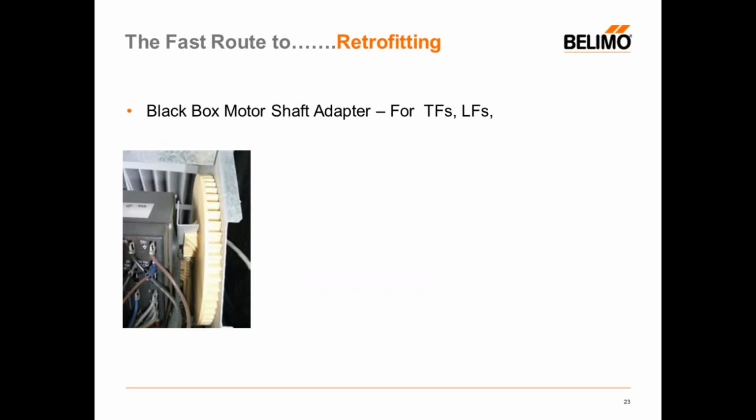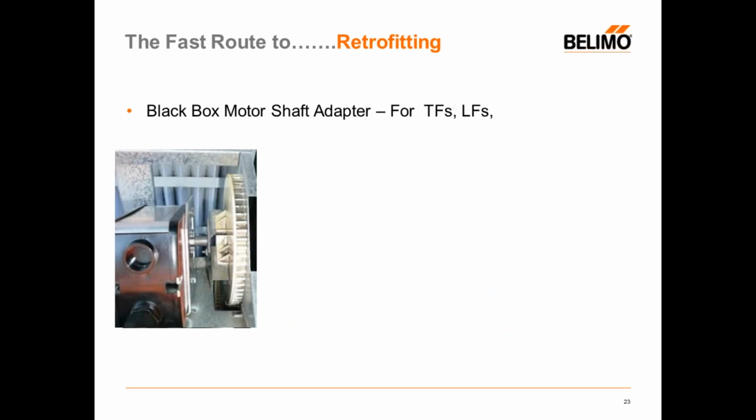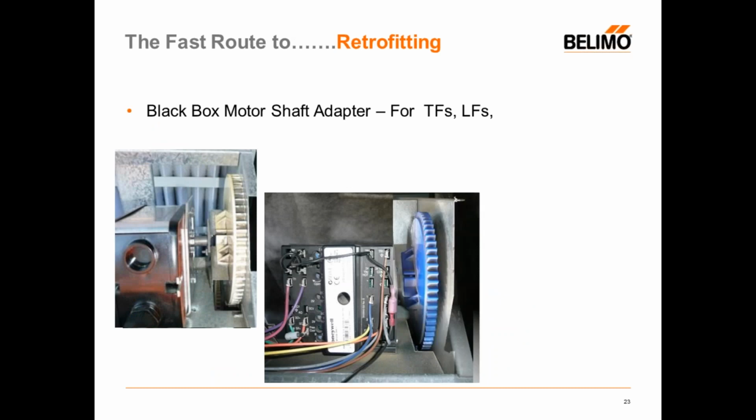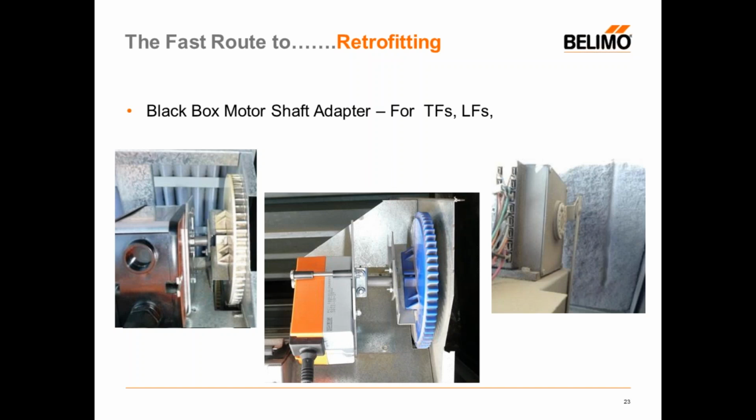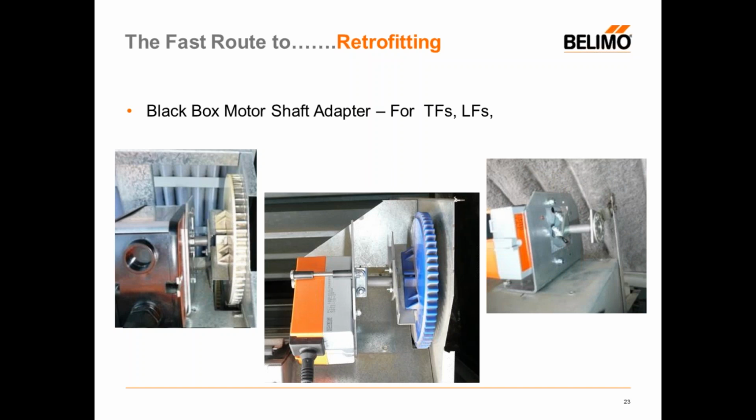Here's a quick look at some job site retrofits. On the left is a Micro Metal economizer assembly that has been retrofitted into an existing Trane unit. In the middle is a Cambridge port assembly retrofitted into a Carrier unit. And on the right is an old Honeywell linkage that was repurposed with a ZIP retrofit kit. You do not have to retire an old unit to gain efficiency.